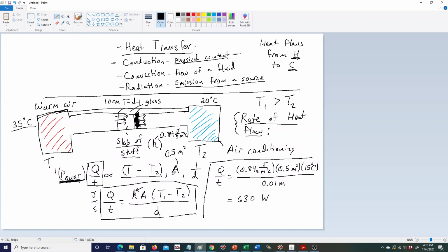You might also say, well, what about the surface area? If there's more area for the heat to flow through, then the heat will flow through better, and you would again be correct. The more the surface area that the heat is flowing through, this shaded part right here, and the face on the other side of the cube that you can't see, the larger that surface area is, the more easily it's going to do so. Or I should say the higher the rate at which it's going to do so.